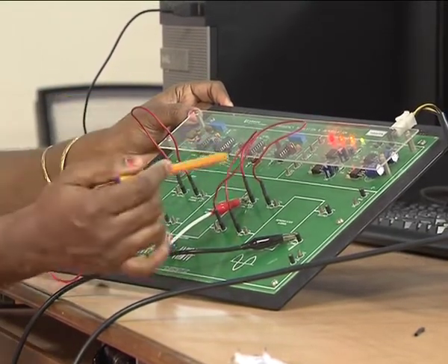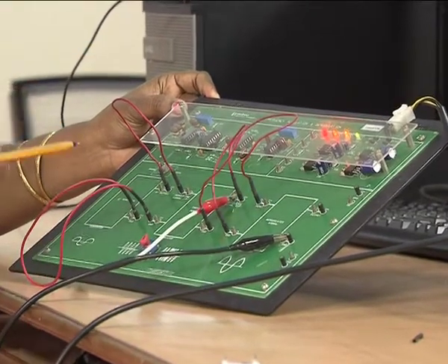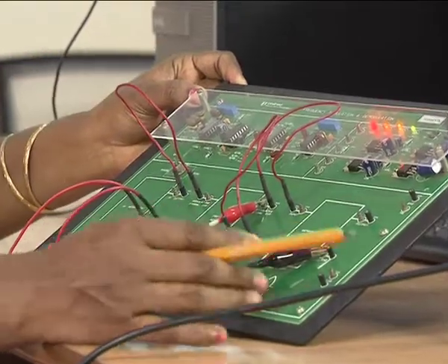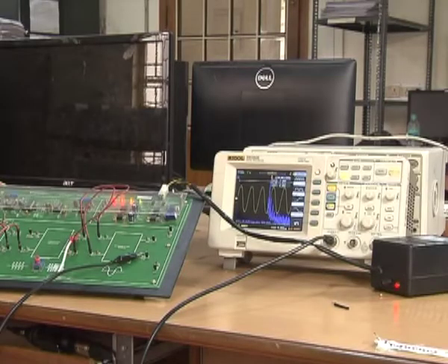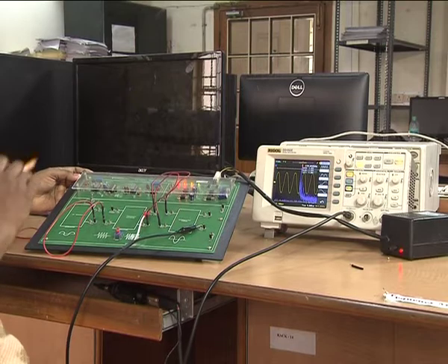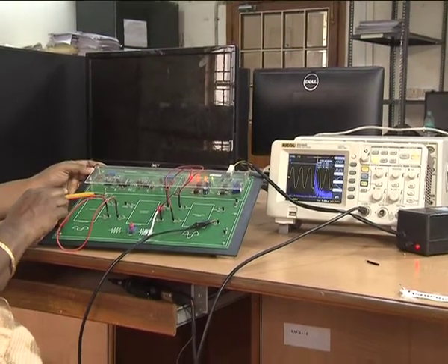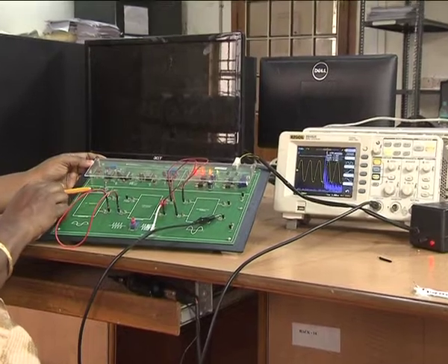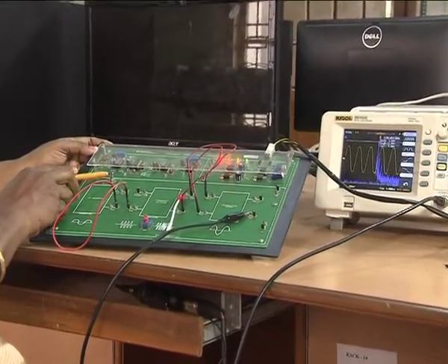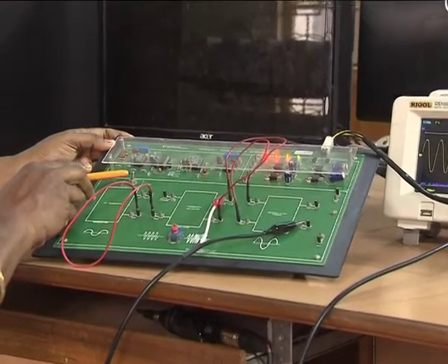And you have one more block, which is for demodulation of the signal. So, first we complete the modulation of the FM signal and then we go to the demodulation part. For the modulation part we have to give an input signal. We have a switch here. We can generate 2 frequencies for the input signal, one is 500 hertz, the other is 5 kilohertz. Presently the switch is at the 5 kilohertz position, so the input signal generated is around 5 kilohertz.